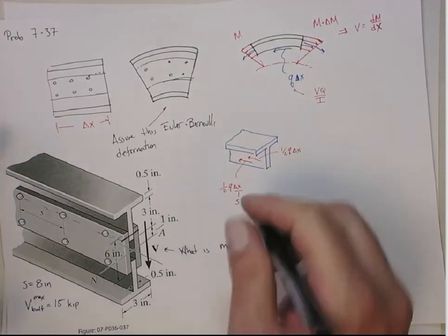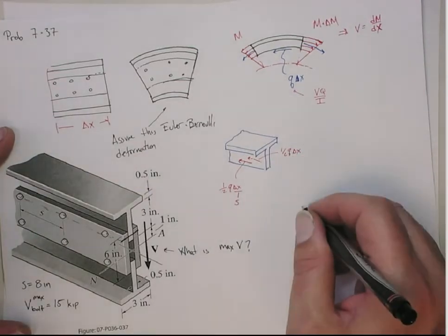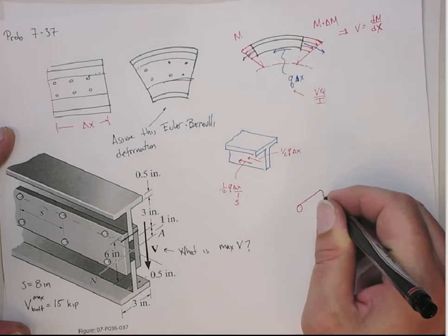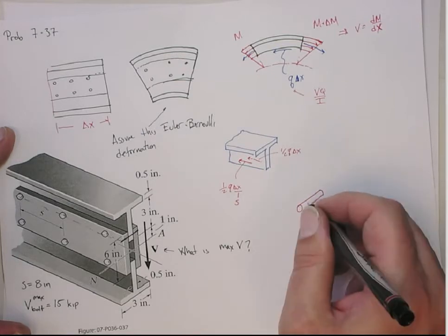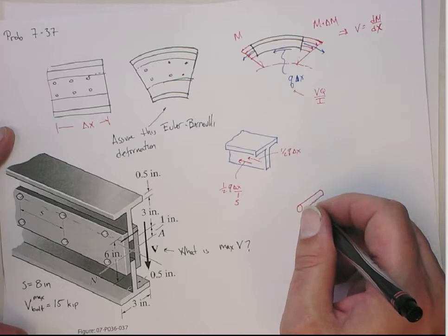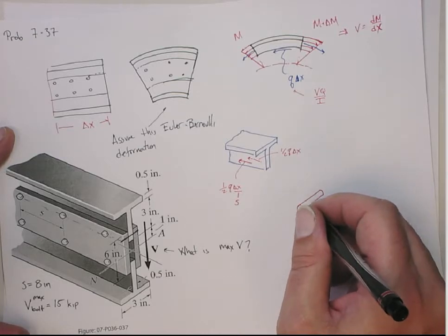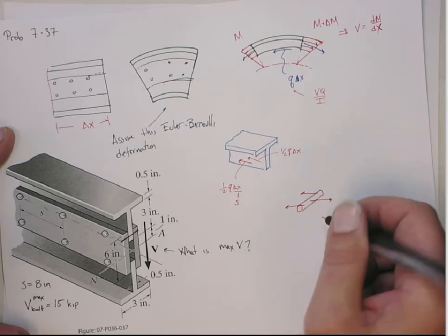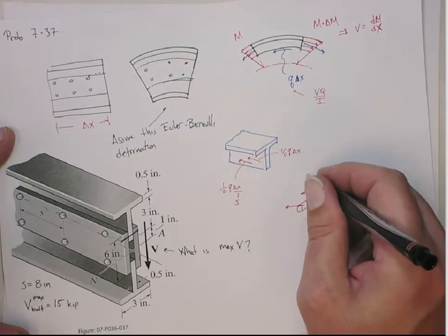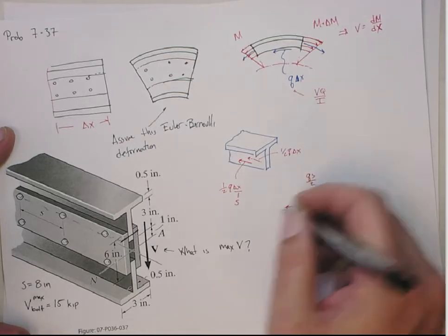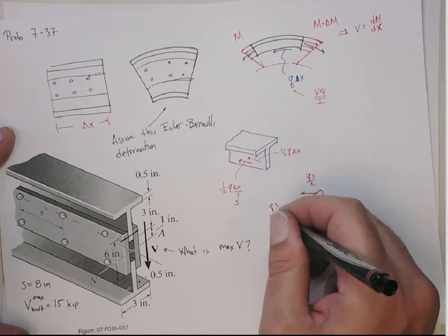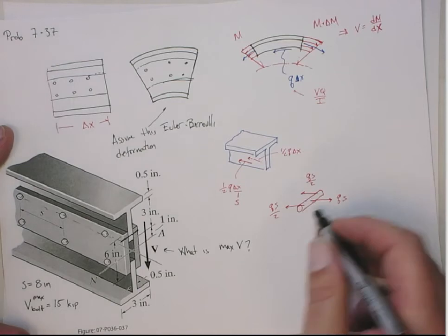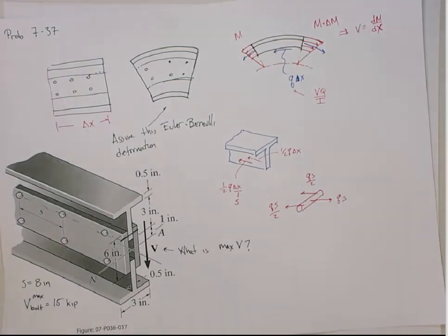The bolt is going to be a double shear. So if I look at the bolt, here's a bolt, exaggerating it a little bit. So basically, you've got a double shear bolt going on, where this is going to be the QS on 2, QS on 2, and this will be QS, right? It's the double shear.